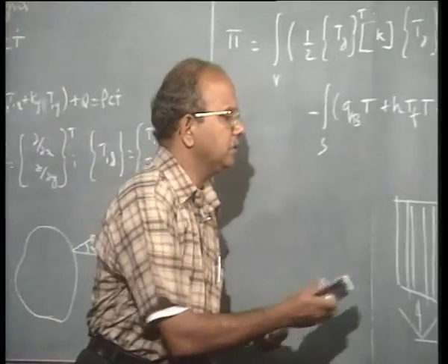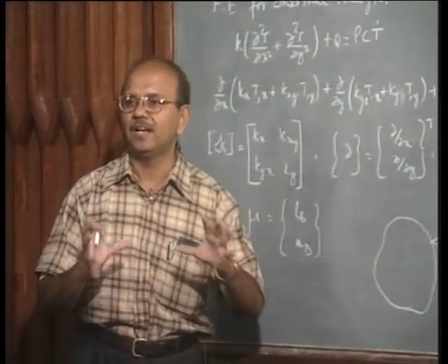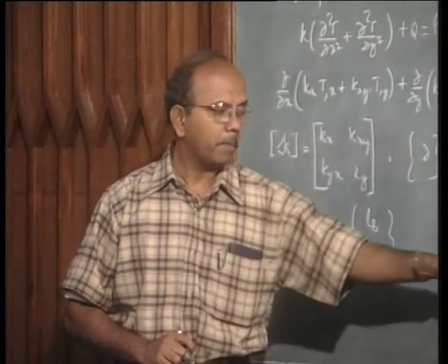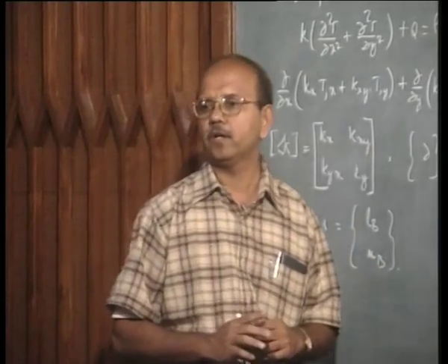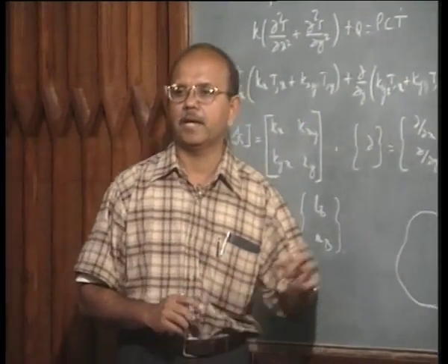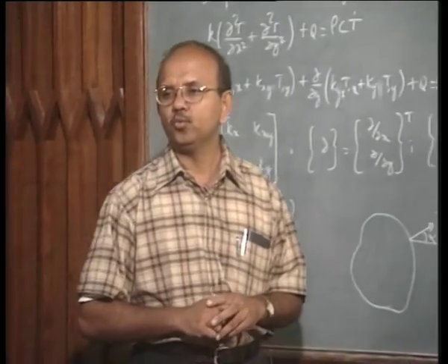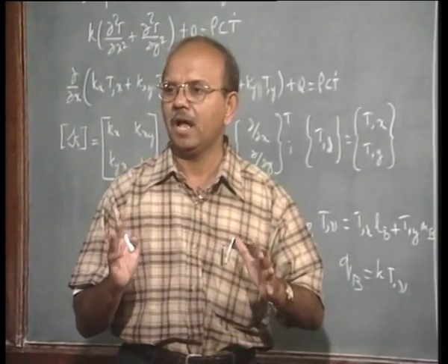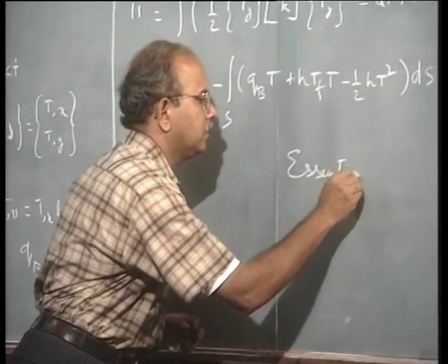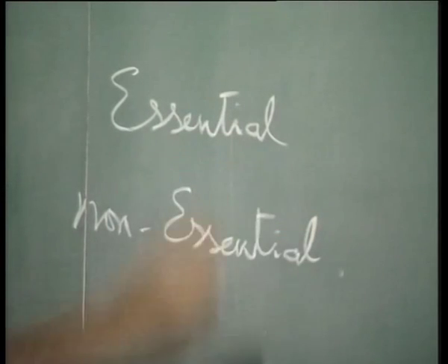Now, is that the only thing? Let's first theoretically put down the boundary conditions and let us look at them more closely in a minute. Now, is that the only way to specify the boundary condition? Convection. Let me capture this from a much more theoretical perspective. The boundary conditions are classified into what are called essential boundary conditions and non-essential boundary conditions.